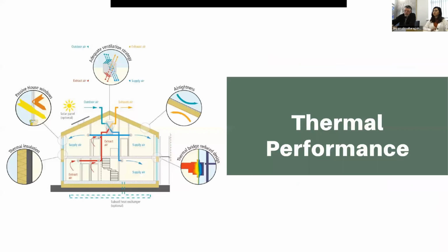The thermal performance of the building: when you have your energy generating heating and cooling and hot water, you have to then look at how you hold on to that as best you can. So the performance of the building envelope is critical. The walls, the roof, the floors, windows, and doors, and that's typically measured in the form of a U value for each element. The chosen fabric will determine how good the U value will be, and obviously the lower the U value, the less the heating or cooling will escape into the outside temperature.